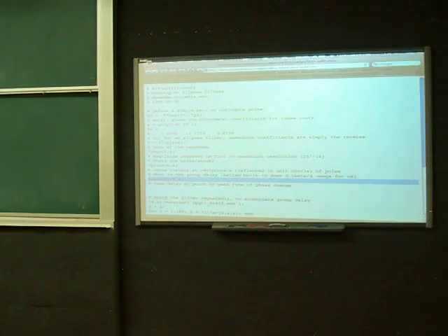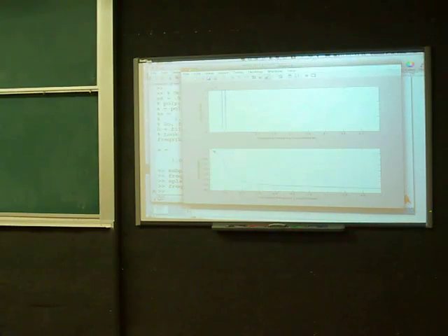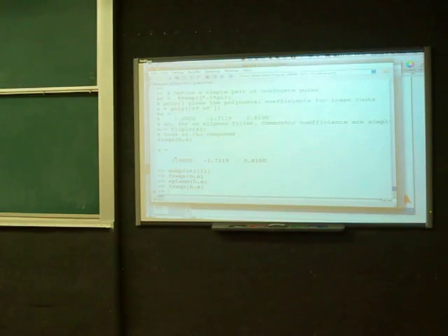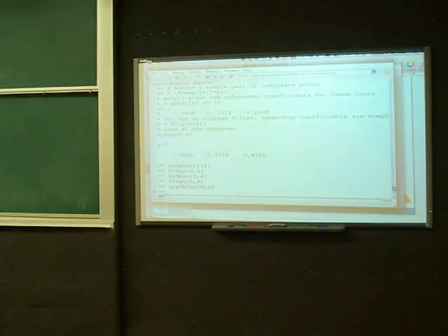Then MATLAB has this function, group delay, to actually calculate the group delay. All it's doing is taking this phase function and effectively differentiating with respect to frequency. But this nicely illustrates that here was the peak negative slope in the phase function, which means that if the group delay is the negative of the derivative of the phase function, that's where it has its maximum. And the group delay, the units are in samples, so it's saying for this frequency at 0.1 of the Nyquist rate, we have a delay of 20 samples, and then the delay is close to 0 for most other frequencies. Now, 20 samples is not a huge deal, but